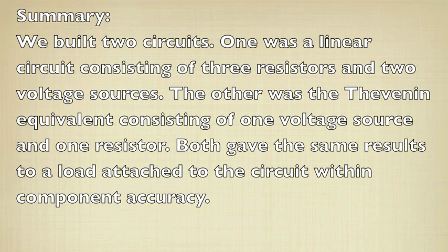Thus, we've seen experimental demonstration of the validity of Thevenin's theorem in electrical circuits and systems, and we see the applicability in that a determination of a load voltage is much simplified if we know the Thevenin equivalent of the circuit it's being applied to.